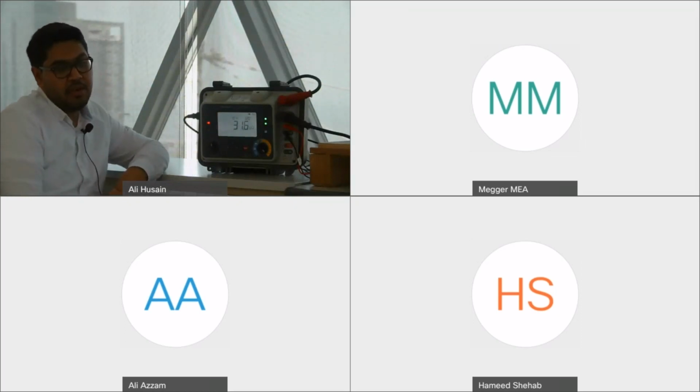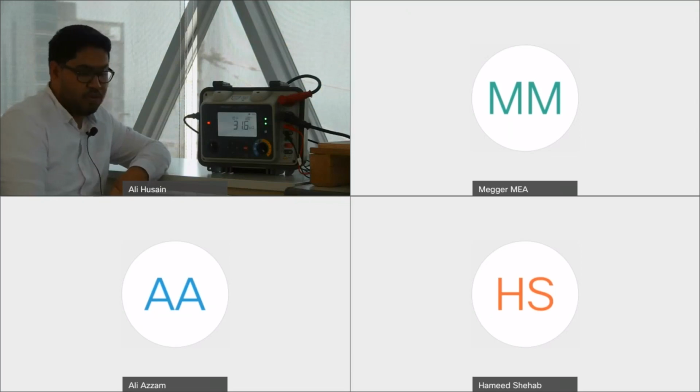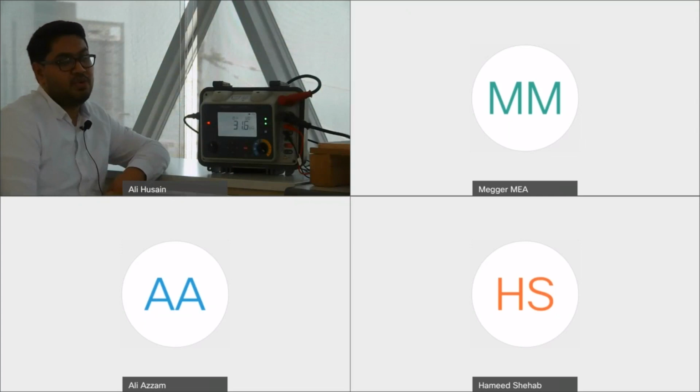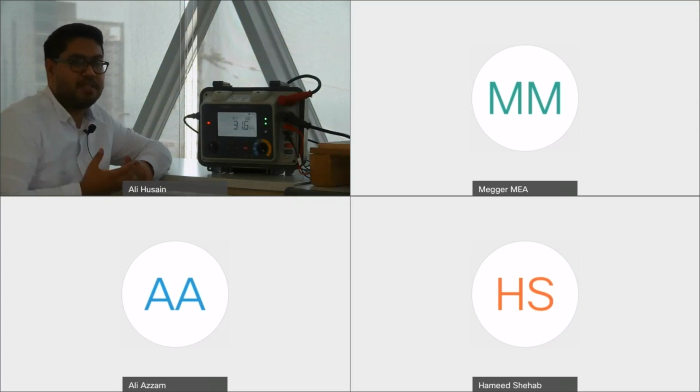Additional things that you might want to do in high voltage circuit breakers, you have the option to conduct what we call a dual ground contact resistance test. Basically, in order to accommodate some safety regulations, and also this is something we recommend, is to connect your test equipment on your circuit breaker when it's grounded from both sides of the contacts.